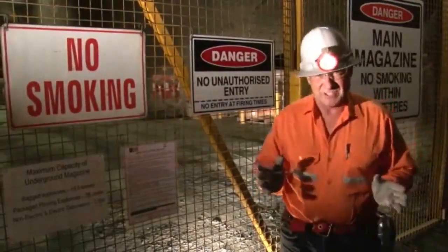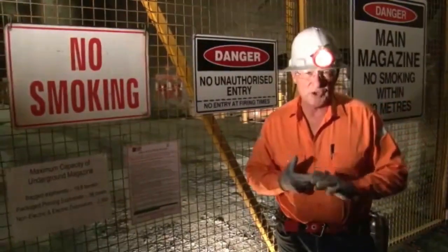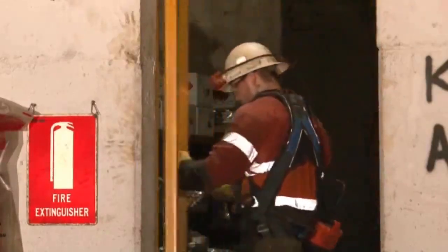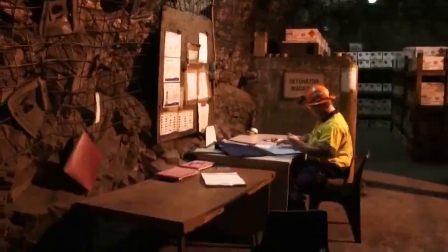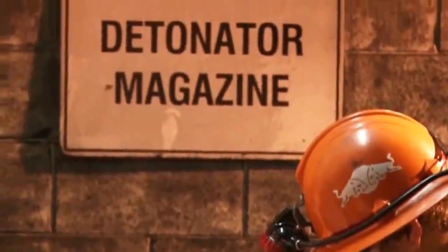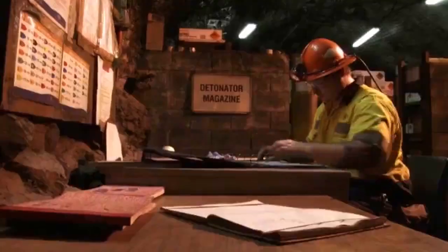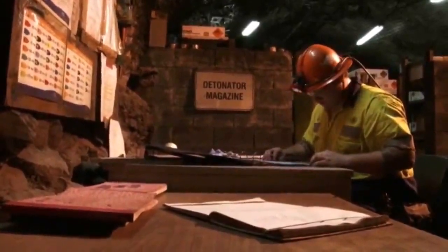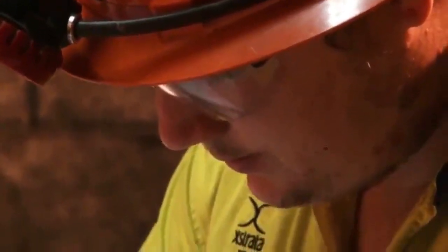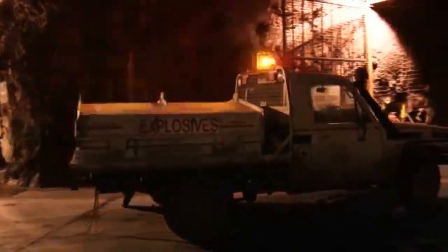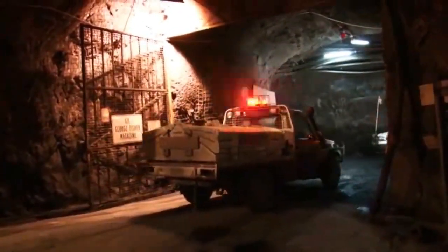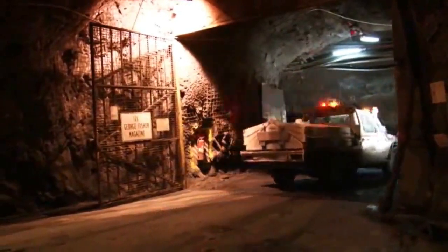Even though explosives are hazardous, if stored, handled, transported and used correctly, they are safe. Explosives must always be stored in authorised areas. The different classes of explosives should be separated by physical barriers. For example, the detonator must not be stored with the boosters, packaged or bulk explosives. It is a good practice to display the storage rules inside the magazines, and only authorised personnel will have access to the explosives. Similar rules apply to the movement of explosives. They can only be transported in approved vehicles driven by competent and authorised persons.